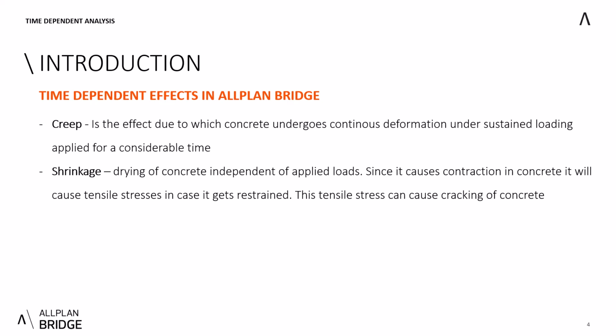And what does this mean? This drying of concrete is basically independent of applied loads. And since it causes some contractions in the concrete, it will also cause tensile stresses. And in case this gets restrained, these tensile stresses can cause cracking of concrete.